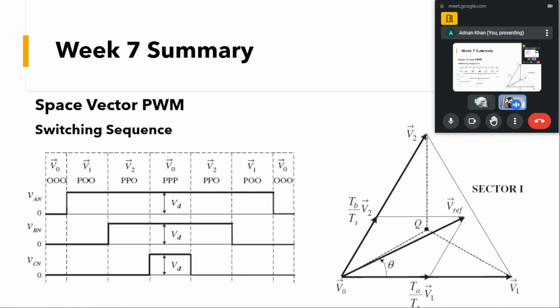That is our motive. We want to have the switching sequence in such a way that we have minimal switching changes in an interval. If you can see, after pp0, if you do ppp, there is only one change, this 0 going to p, and subsequently pp0, that means only one change is happening as p is going to 0, and so on.